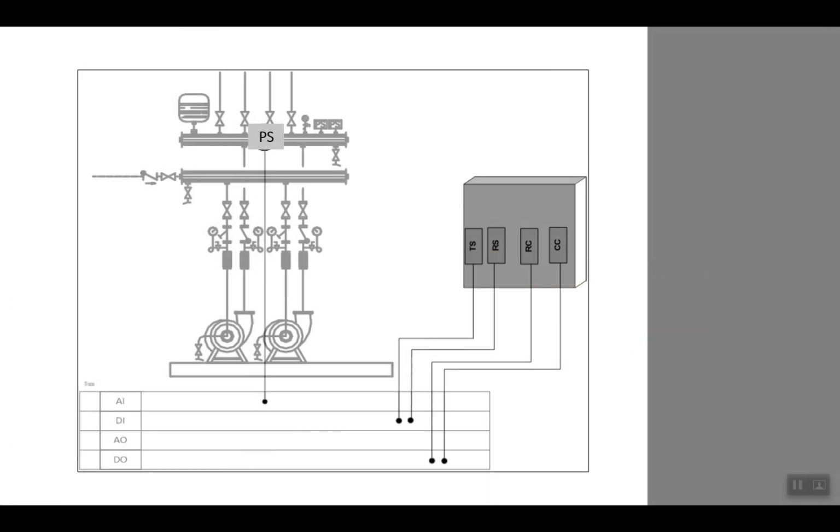So let's start. In this picture you can see the schematic figure of the booster pump in the mechanical room. The most important part is that we should read the pressure at the collector supply to the building. So we should make sure that the pumps work fine. So we read it, and we need an analog input for that.